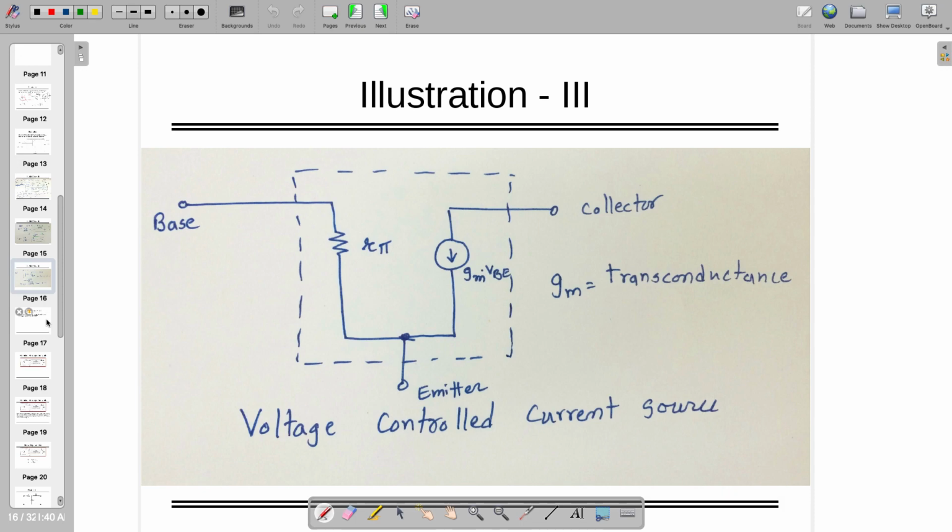If I replace all of them in the two-port network, I am going to see this one. If you remember, at the initial time we used to draw this, right? So your transistor is like this. Wherever you are saying transistor, you have to replace it with this structure. But this is possible when it's Y parameter. You can replace the same thing using Y parameter but with a T network.